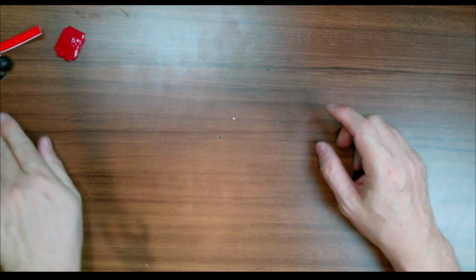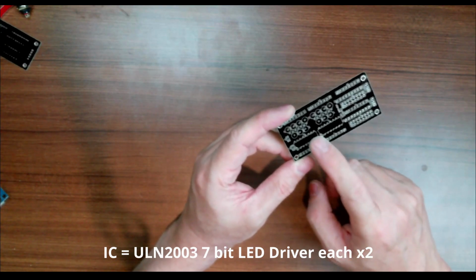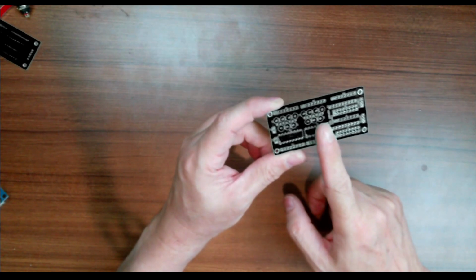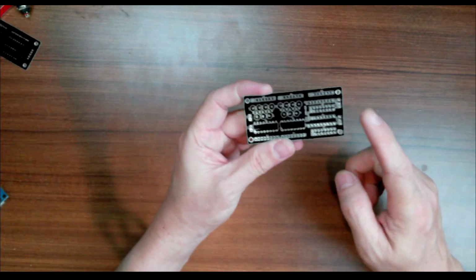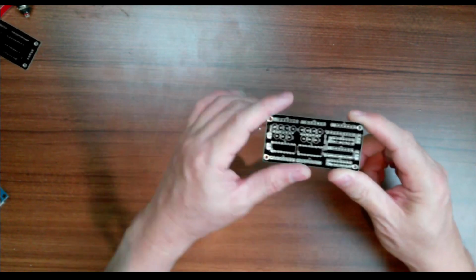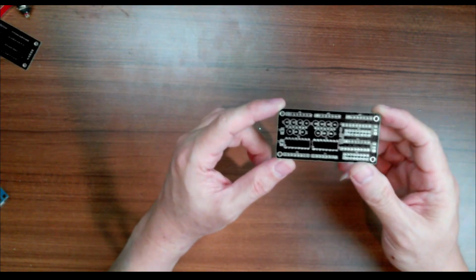The other driver is using ULN type, so it's just manually using a resistor here, and the ULN2003 chip is here, IC, and then it drives only 14 LEDs. Just this one is for the pull up resistor before you connect this one into the Arduino 2560 input. So this one's for the input, this one is for 14 bits output, driven by the Arduino 2560 directly